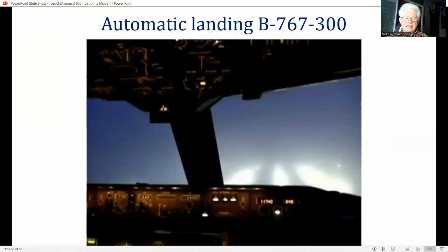Completely blind landing can be performed with a HUD system displaying synthetic vision guidance and primary flight information, given that the required integrity is provided. This can be achieved by the addition of a second means of monitoring, which can be either a second HUD channel or, more realistically, the addition of a fail-passive autopilot.